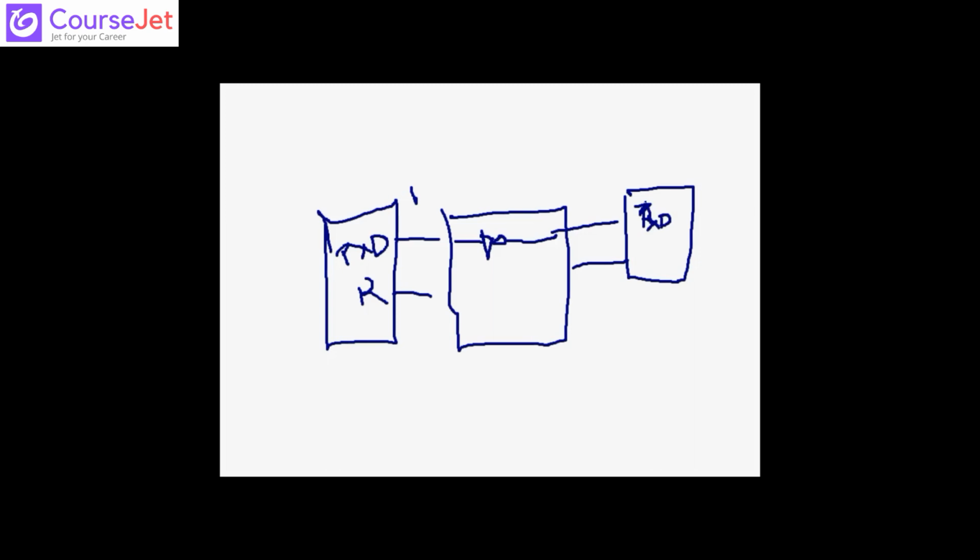So basically this is your input and this is your output. Again, this is your main input and this is your main output, but here you will be sending one signal and receiving another signal. Here you call it TTL logic, which is 0 to 5 volts logic, and here you call it RS232 logic, which is from -3 to -25 and +3 to +25. It is not going to change your signal, it will simply transmit the same thing.